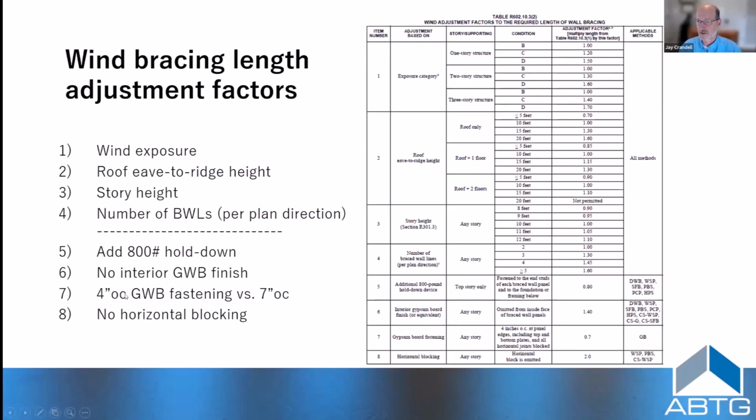I've had to do this on some houses that were built wrong because the bracing wasn't planned ahead of time. This provides a simple solution just by adding additional fasteners to gypsum that's already there, remudding the wall, and you're good to go. It doesn't get you out of jail free all the time, but oftentimes that helps. Better to plan that in while you're designing and putting your plan forward than later.